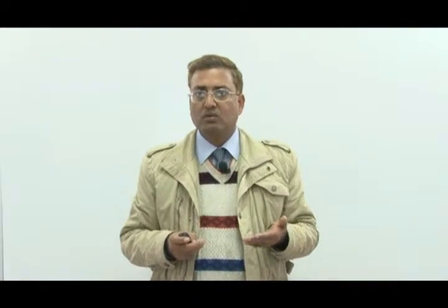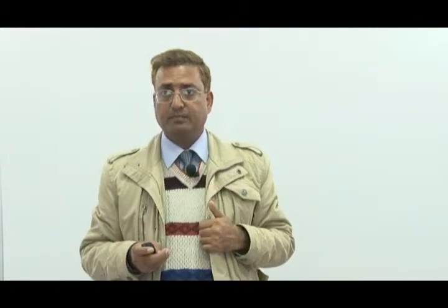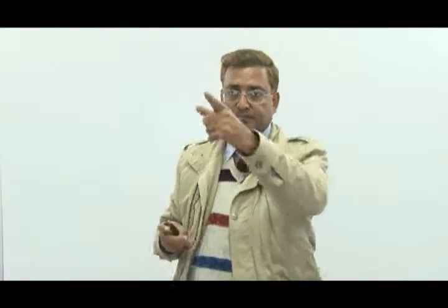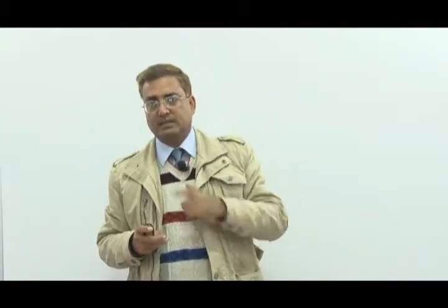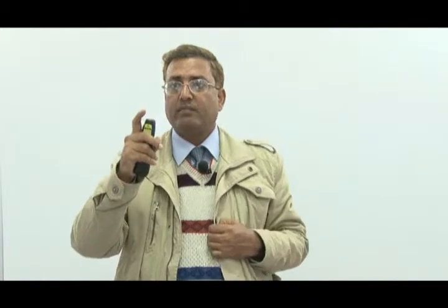So if you take the natural coordinate system, that means from XYZ coordinates to zeta, eta and xi, this mapping can be established, as shown here. So you have now zeta, eta and xi in the natural coordinate system, and the corresponding nodes become as shown there.